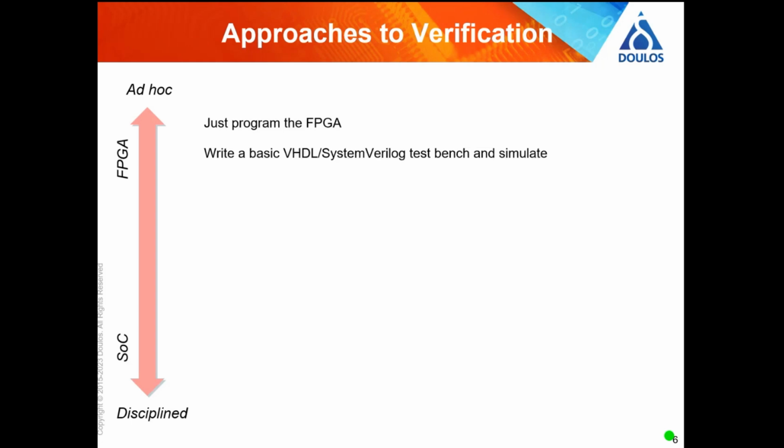Really, the very minimum you should be doing is writing some kind of basic test bench. So you've got your code that is your design, and then more code that at the very least generates inputs to your design. Because just programming the FPGA is rubbish, because you can't very easily control the inputs to your design. You can't very easily observe the outputs. If there is a bug, you might not spot it. It's just a very poor way of doing verification, but it's an excellent way of doing validation, as I'll mention in a second.